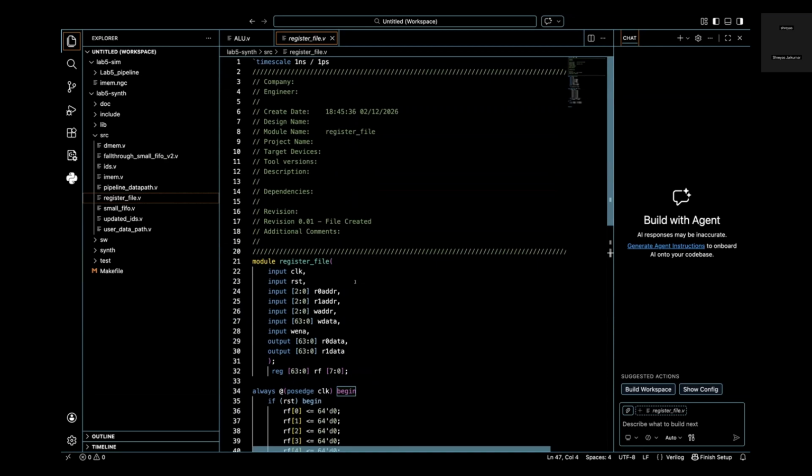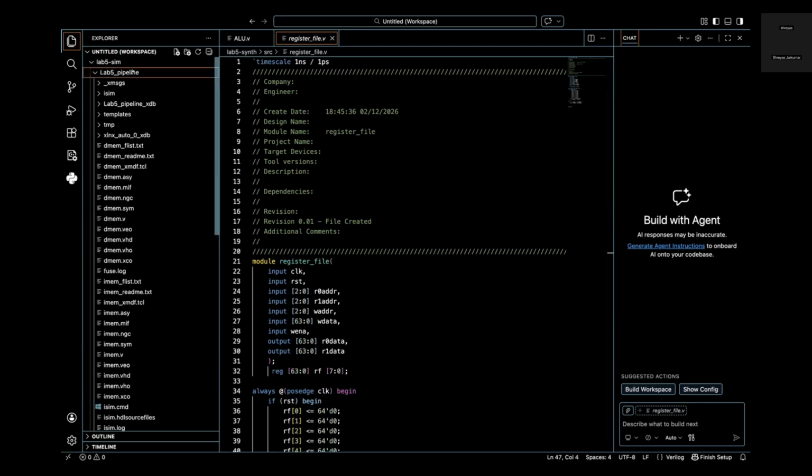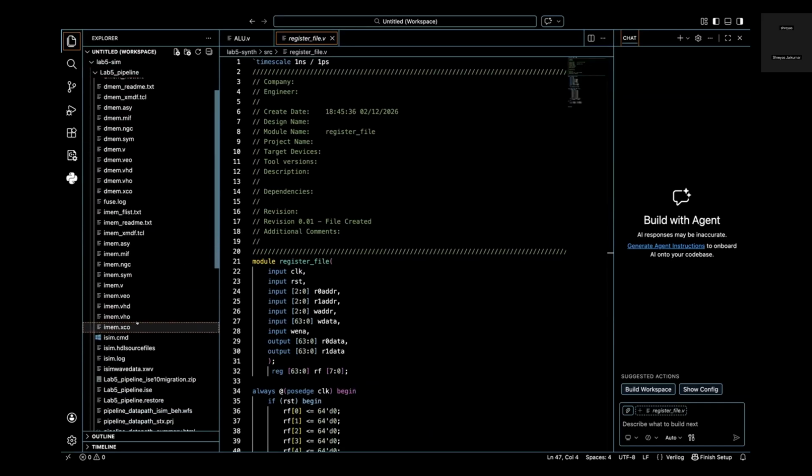And our instruction memory is 32-bit width and 512 depth. They have given a choice of also considering 16-bit width and 1024 depth, but we went with 32-bit width and 512 depth because that perfectly suited our ISA. That's our instruction memory. I'm just going to quickly open this, and as you can see, there's a bunch of files over here pertaining to DMEM and IMEM.